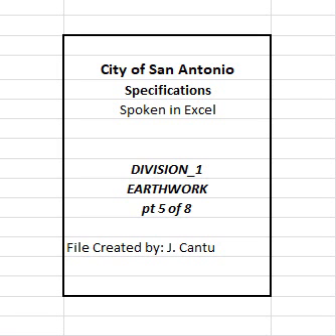Complete preparation of the right-of-way, in accordance with Item 101, preparing right-of-way, for areas to receive embankment. Backfill tree stump holes or other minor excavations with approved material and tamp. Restore the ground surface, including any material disked loose or washed out, to its original slope. Compact the ground surface by sprinkling in accordance with TxDOT Item 204, sprinkling, and by rolling using equipment complying with Item 210, rolling, when directed.